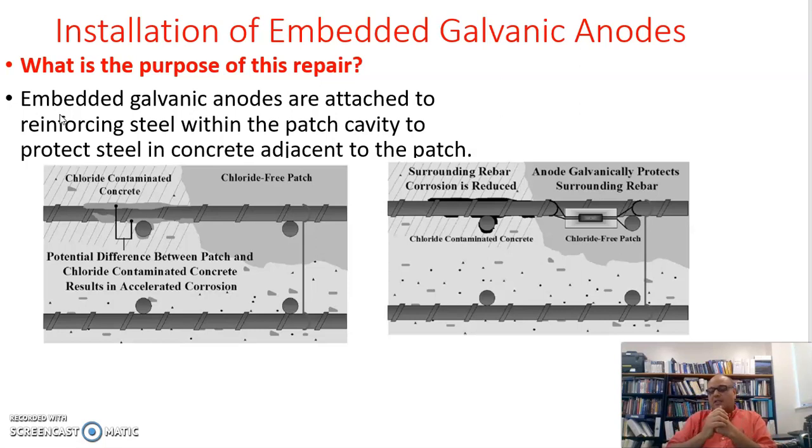There are several things there, but I want you to focus on what causes this kind of corrosion, and you can dedicate a whole presentation that you prepare, and I'm going to critique it, and I'll be hard on you on this as well. It is about the corrosion caused by, let's say, the chloride ions in the air. Corrosion is also caused by the carbonation of the concrete itself. And what is that corrosion? It's a galvanic kind of cycle, an electrochemical process of corrosion.